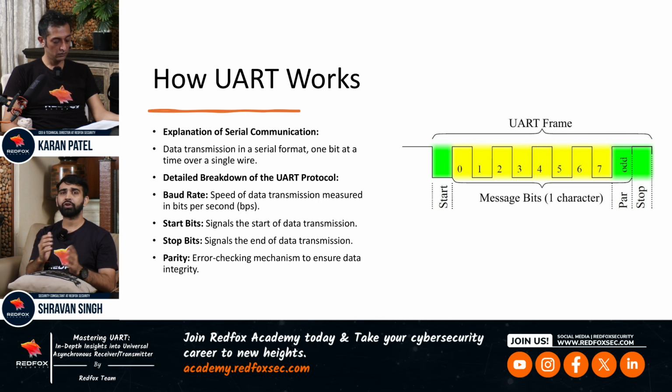So this is how UART works, consisting of the start bit, stop bits, message bits, and along with that parity bits. And the baud rate should also be known, because of that we can have human readable data.